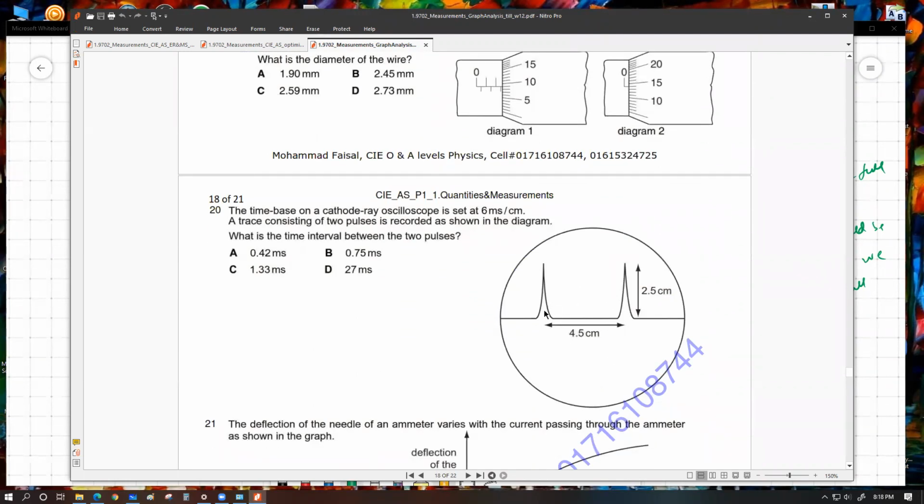Every single time the magnet will pass close to the solenoid coil, it is going to give us a pulse, kind of EMF spike, because whenever the magnet is going to cut across the wires, cut across the loops of the coil, then we're going to have an EMF generated. And then for the significant duration, when the magnet is rotating further away from the coil, we might as well have no EMF generated. Then as it passes close to the coil, we're going to have another spike of EMF. So this is the type of graph we're going to see.